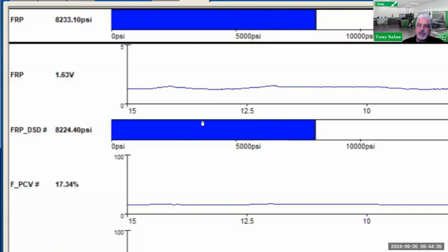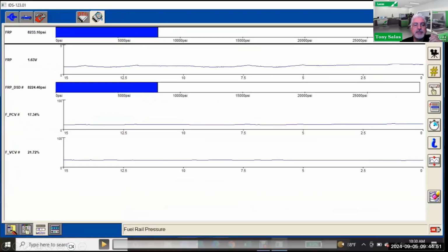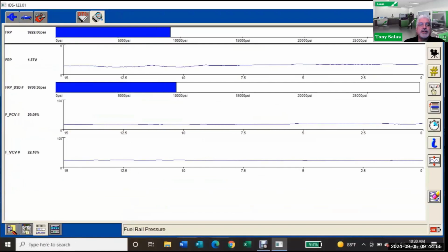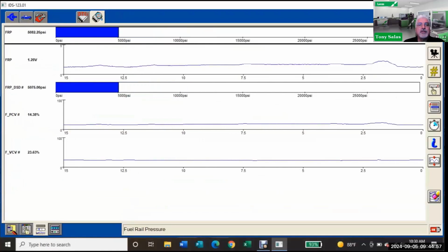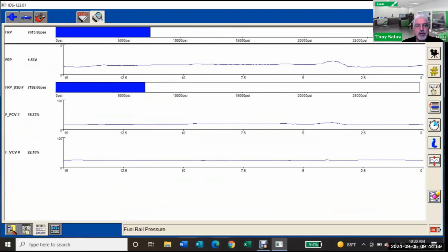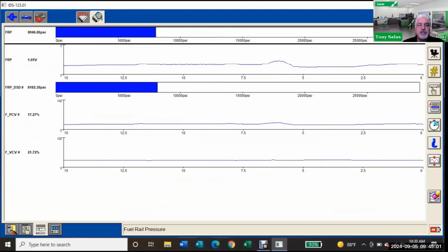So Power Stroke 6.7 does that, Power Stroke 6.4 does that, and even the Ram 6.7s do that. Okay, so in this case, this definitely tells you again that you definitely are in a default value. We'll get more into default, but for now, what I'm just trying to show here is, again, you can look at signals right there. Definitely we can see how that rail pressure went up and went down as I'm testing this truck.